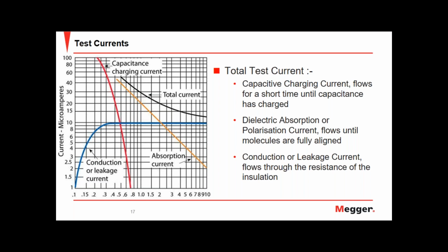Now, understanding this concept, moving on to the dry type insulation, PI test is very commonly performed on dry type insulation. You talk about motors, generators, and many other dry type transformers, many other assets that have dry insulation, either epoxy or resin based or a combination of epoxy mica, and all of these are valid to test with PI.